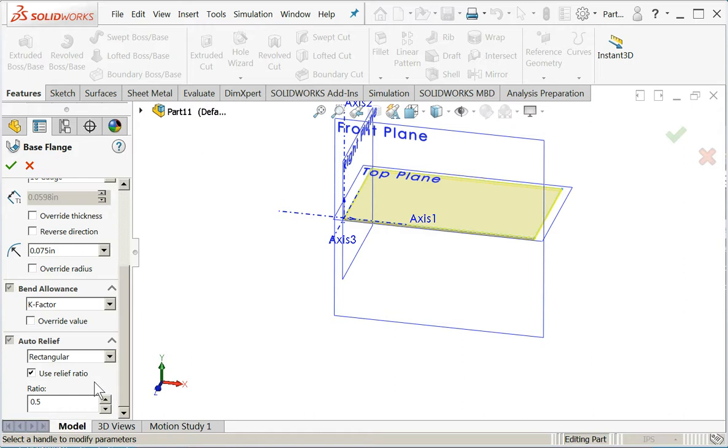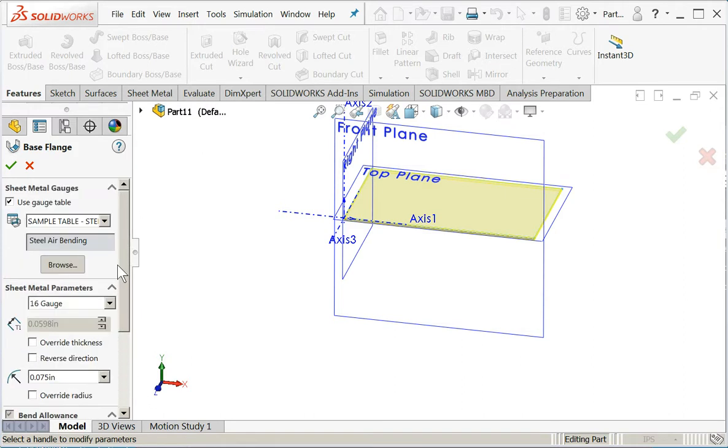So if you were to actually mathematically figure out all your center lines and do the dimensions for what you thought a flat pattern should be, it would come out wrong. You'll find that you have to take the stretch of the metal into consideration to get an exact object post-bending. But let's keep going. We'll just keep that in mind.